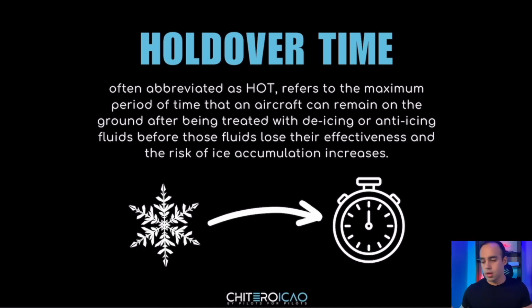So after they apply the fluids, they clean up the aircraft, they put everything there, they perform the anti-icing procedure. You need to be at flight level 300 or something like that in 1 hour, in 2 hours maybe, I don't know. Because the fluid's gonna wear off, the liquid's gonna wear off.